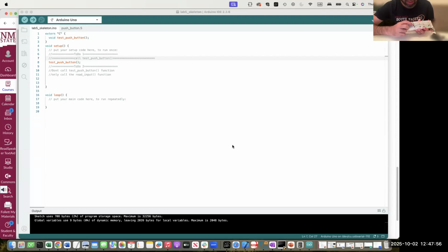Remember, W and Y are connected anyways, but the pair on the other side, on the left side, are not connected. That pair will be connected with the pair of W and Y only when I press the push button. So if I press the push button, you see that all the LEDs are switched on. This way you can figure out the right way to connect the push button. So that is the first task of the lab, and it carries 15% points.